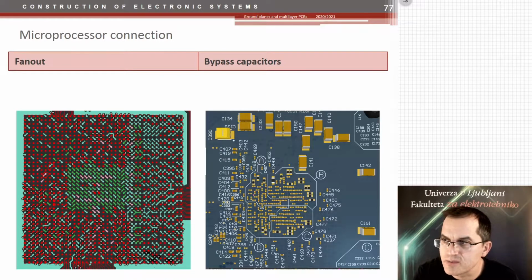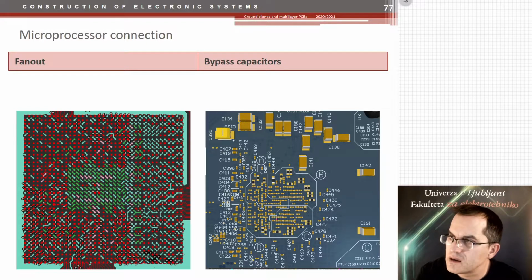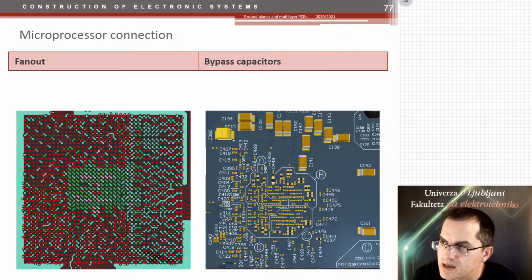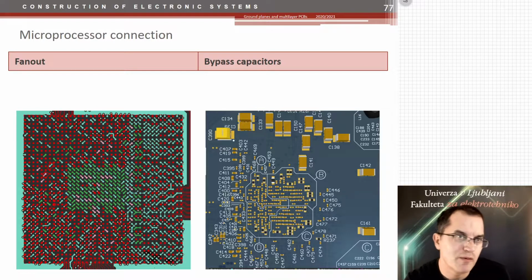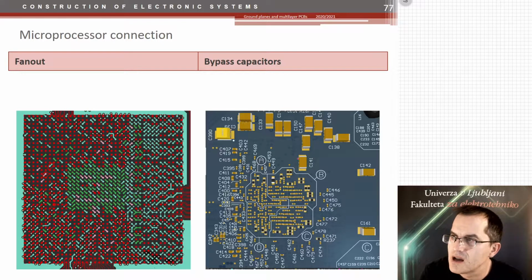There are 4 different power supplies for this IC required, A, B, C and D, and these all are bypassed by this bypass capacitor. The smallest are the ceramic capacitor just below the pairs of ground and power supply, here, here, here, here, here. And the big ones, which are the bulk capacitors providing the low frequency power to these high frequency bypasses, are here. Also the tantalum, the one which has a lower quality for resonance damping.